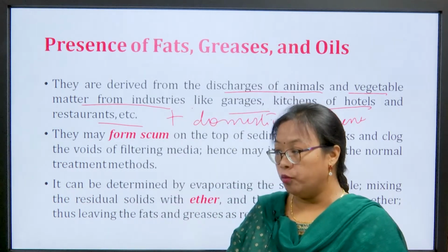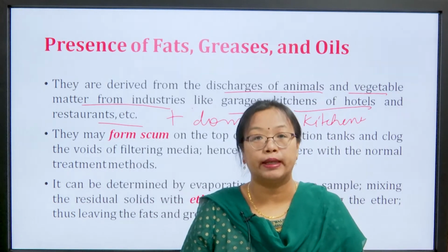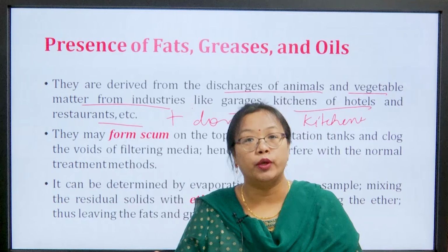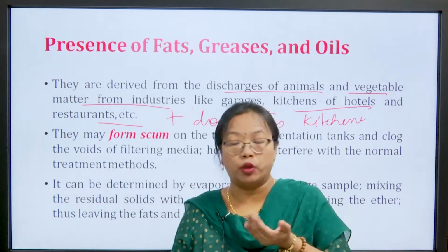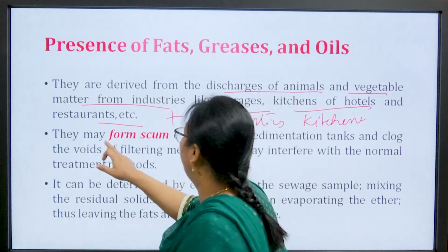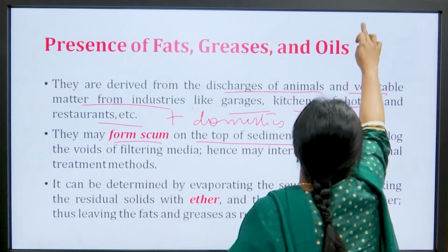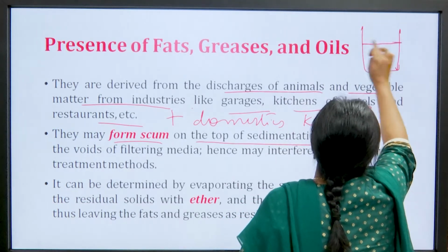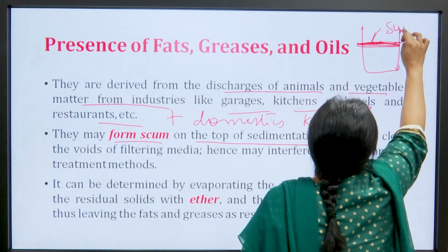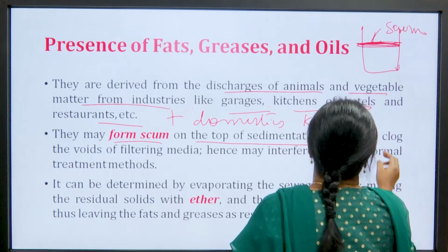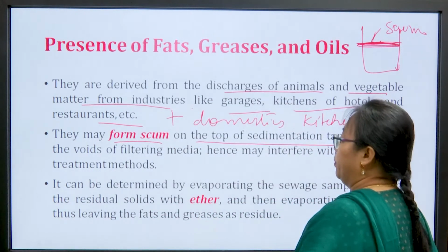When this oil, grease and fats get mixed up with the wastewater, they are going to come up and settle on top of the wastewater. They may form scum on top of the sedimentation tank. Because it is lighter, they are going to form a layer here, and clog the filtering media, hence may interfere with the normal treatment methods.